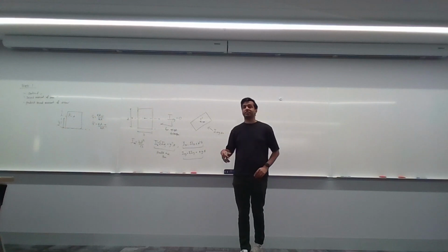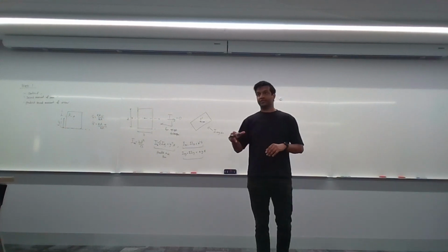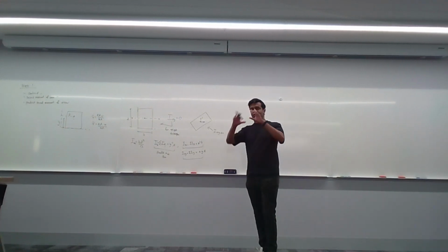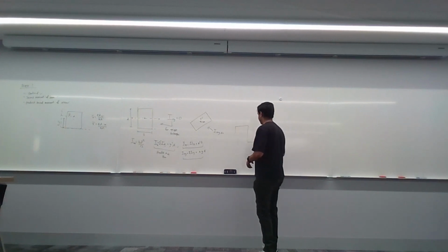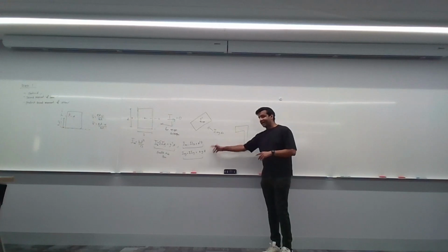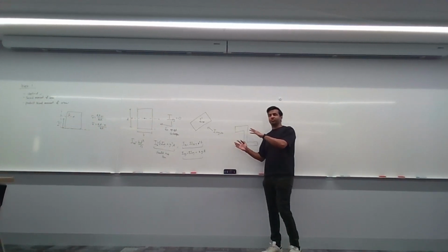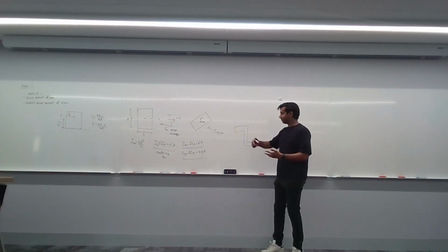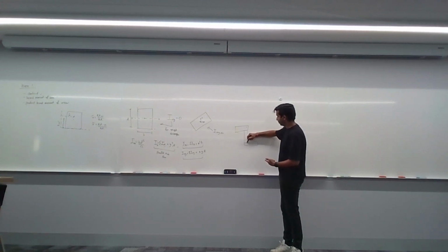Now what you might remember is from the workshop questions that you would have done for this topic. Say you have a Z shape like this, for example, that's your composite shape, right? And you had to calculate, let's say, Ixy for this shape. What would you do? You would split it up into different parts. So let's call this shape 1, shape 2, and this is shape 3.